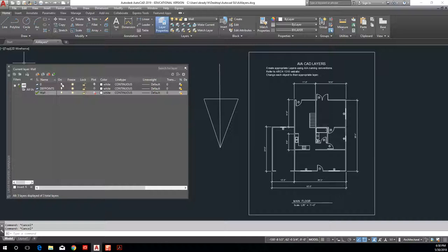We don't want to accidentally draw things that are not visible. And it may not seem like a big deal, right? But if you accidentally draw something and then you turn the layer back on and you have 400 more columns in your drawing than you thought, and your project goes out to the contractor and they're like, hey, there were supposed to be all these random columns all over the place. And you're like, no, those weren't supposed to be there. They were supposed to be turned off in the AutoCAD drawing, right? You guys get the point. Mistakes can really easily happen when you do that kind of thing, and we don't want that to happen. So don't use this functionality, use the freeze thaw option, okay?